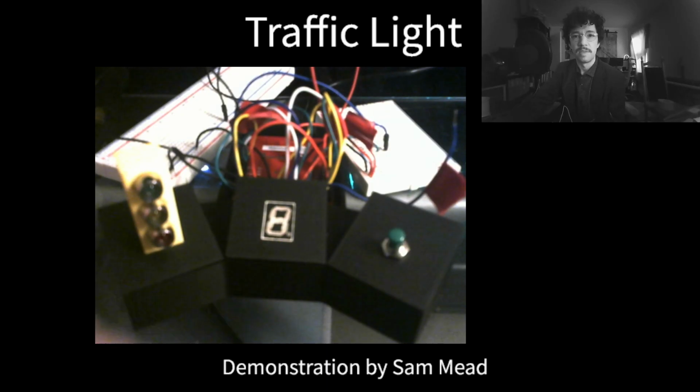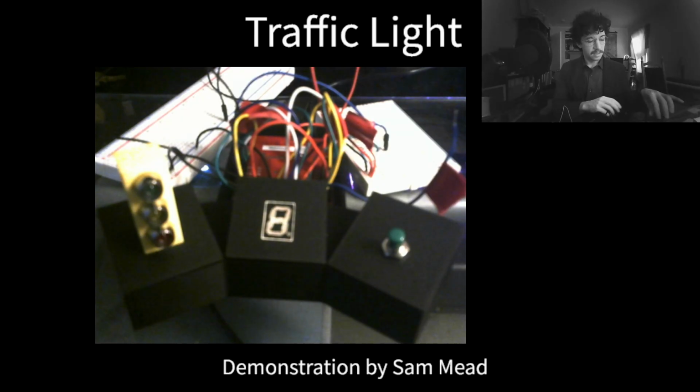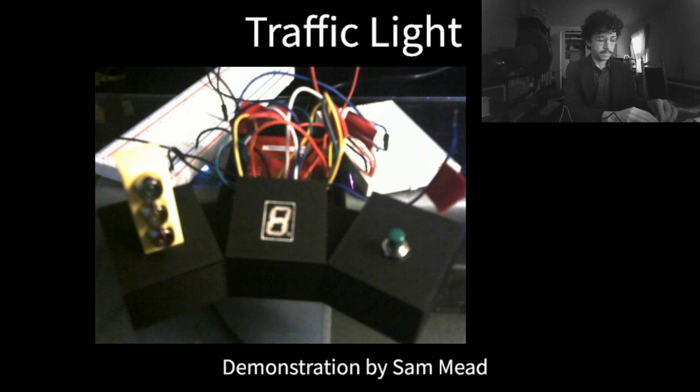And we also have the switch, which is on the right side, and will control the pedestrian input, because this will be implemented essentially as a Mealy machine. And that is also on port F, taking the place of the internal switch, using PF0. So we will go ahead and get this going for a demonstration.